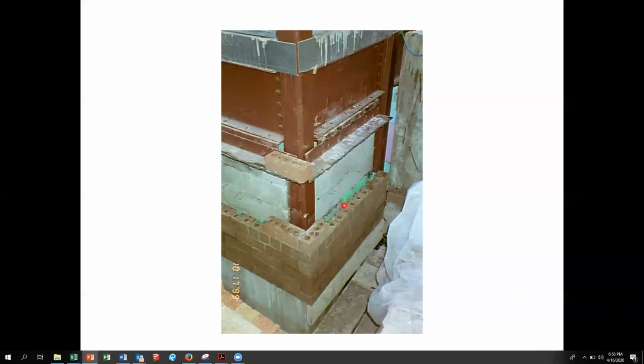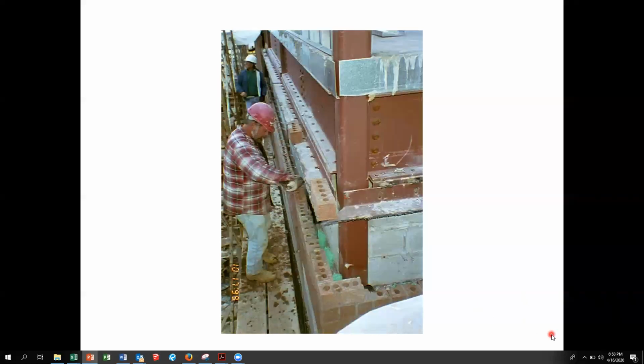That is called mortar net. So when they are laying brick and mortar gets in that air gap, if you plug it solid, it's going to be a bridge for water to connect from the brick to the block and then eventually inside the building. So that catches what we call, the technical term is snot. Sorry about that. But it's the mortar droppings. And so water has a chance to kind of meander its way around this. It's almost like plastic honeycombing. It's creating channels. Exactly. And it's called mortar net, as in fishnet.